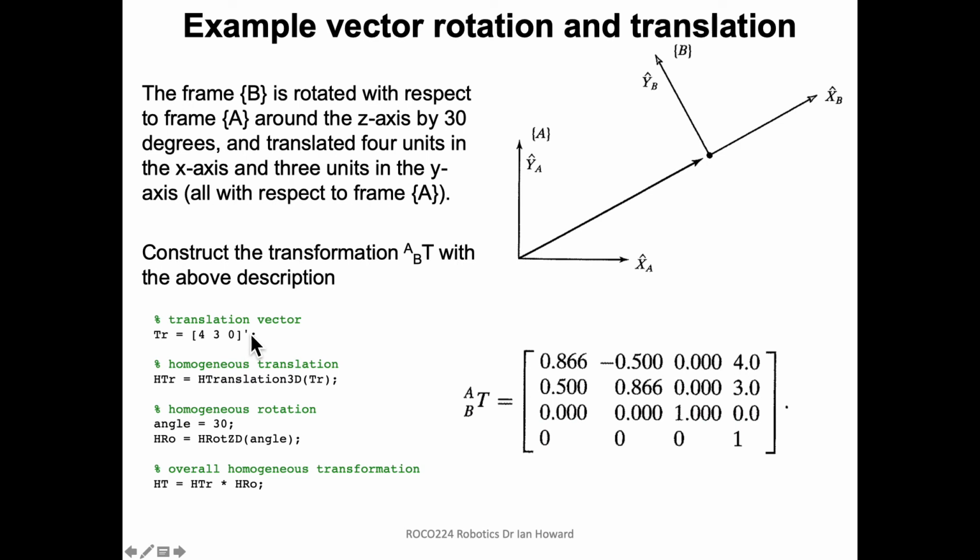And it's always very good practice to make sure that when you're doing these kind of things, the vectors you end up with are actually of the right form to fit in with the theory. Otherwise, you'll be going through things by hand and flipping things up and down just to make sure they all work. Then we get a homogeneous transformation of this, and we could have done it by first principles and just put an identity matrix in and then concatenate this at the end and then put obviously the last row in.